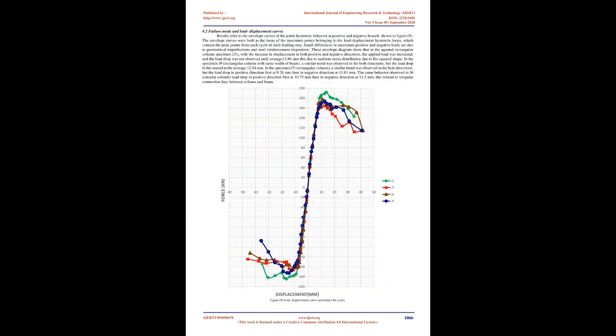During the tests, as shown in Figure 8, diagonal cracks appeared along the beam, located particularly close to the connection with the column. Some cracks occurred in the joint panel. Failure occurred between beam and column face. Yielding of steel reinforcement bars in the beam occurred at an early level of displacement, about 6 mm, before cracking in the panel joint. The final failure mode was due to the formation of the flexural plastic hinge in the beam end, adjacent to the column face.